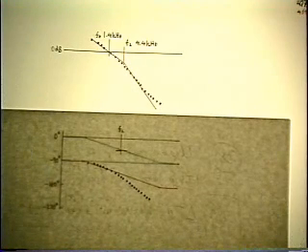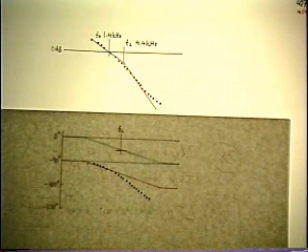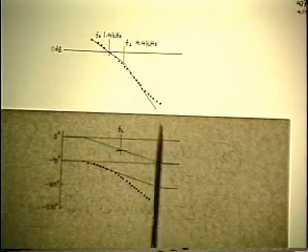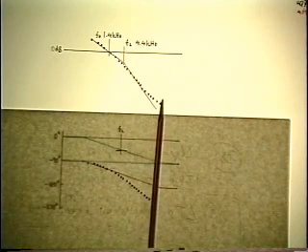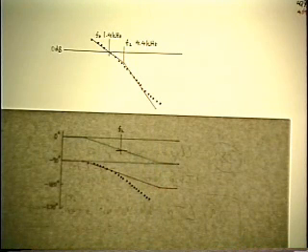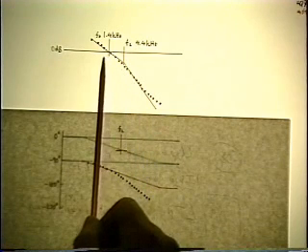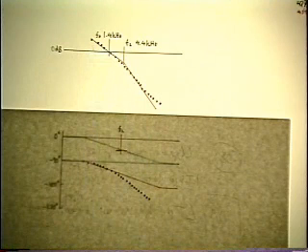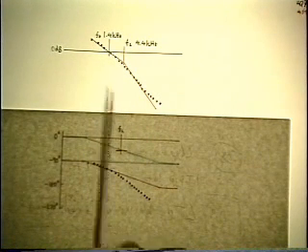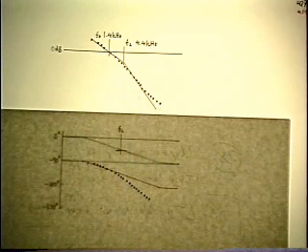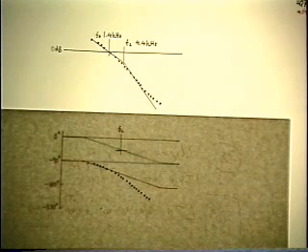So what are we going to do about that? And your first thought may be, well, why bother? Because the deviation is a concave upwards corner, so we have a 0. And the 0 will give a little extra phase lead down at the crossover frequency, and so we'll improve the phase margin, which was already 73 degrees. So we needn't bother finding out where the 0 comes from. Let's just ignore it and go on and get production rolling.